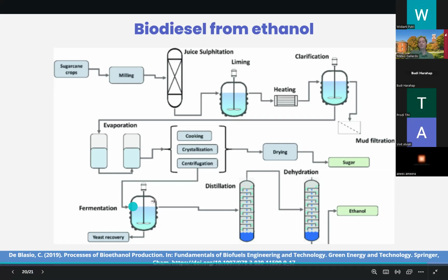After the fermentation, we produce ethanol, and it is concentrated in distillation processes and then purified in dehydration processes. Usually in these stages, we use zeolites to trap any small particles and purify the ethanol to get more than 97% ethanol even.